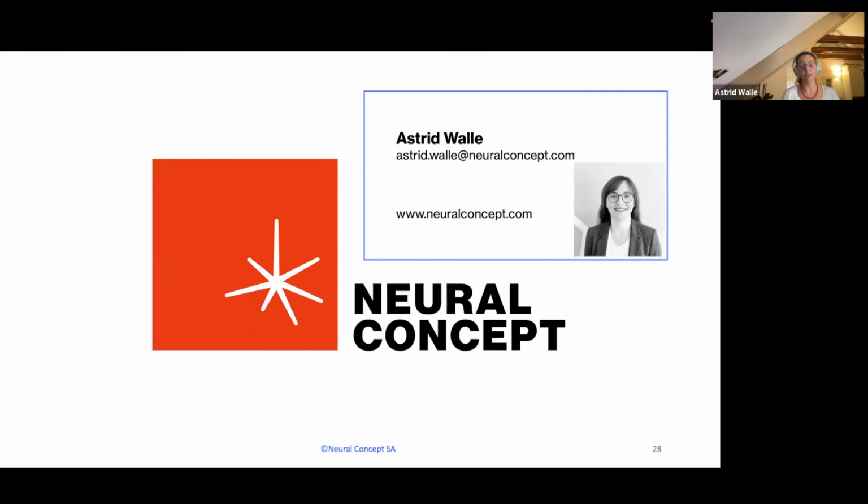This is actually also something the model itself will tell you, because alongside the prediction, it will also give you a confidence index, a confidence interval. It will say, okay, from the overall design space which I have seen during training, this presented geometry is really far off, so do not trust my prediction; better run a simulation, feed this additional data point, and retrain me with it. Or if the new geometry lies well within the envelope of the training geometries, it will say, I'm super confident that my prediction is right because I have seen other samples in the same area of the design space.